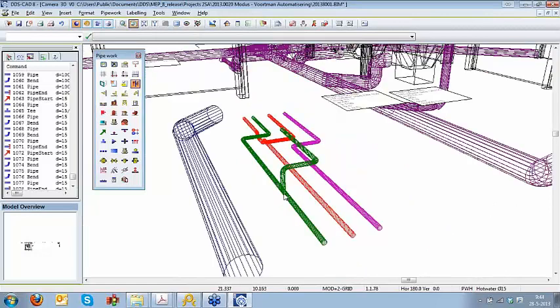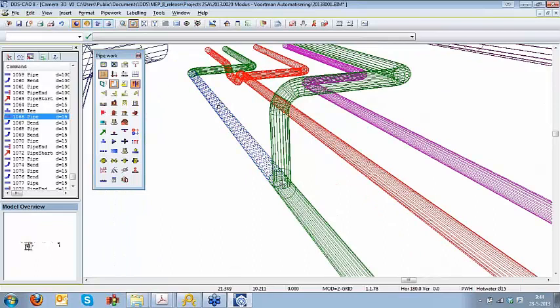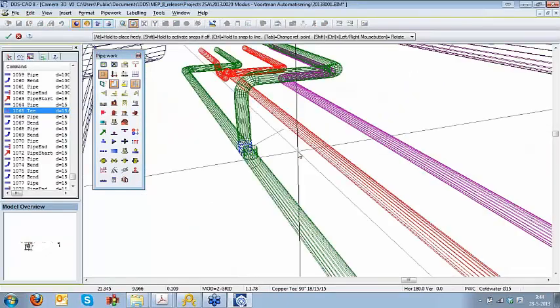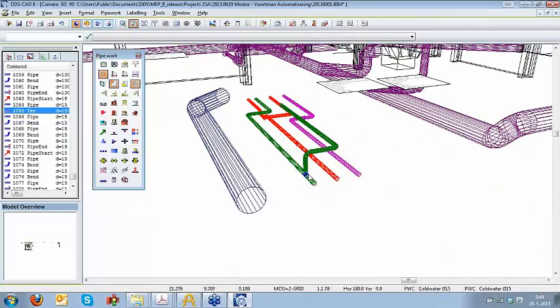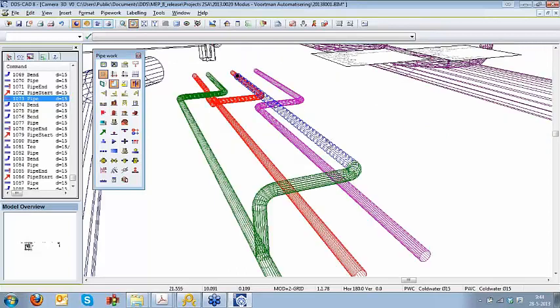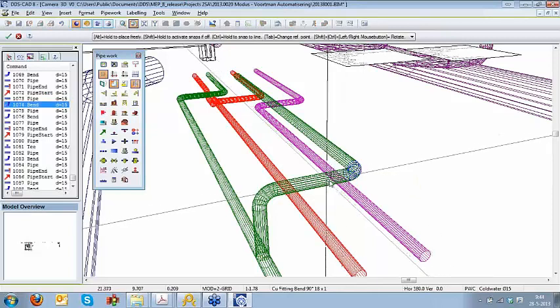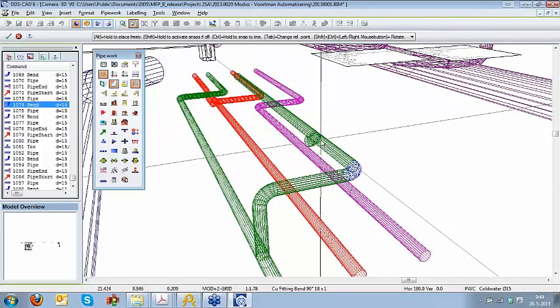I will show you from my T, if we would like to have the T changed in position or direction, we can move the T into the string. So when we select the T and move it, we can see that this pipe element in the background on cold water is changed. And if we would like to have another placement, we can select our bend and move the bend into different directions.